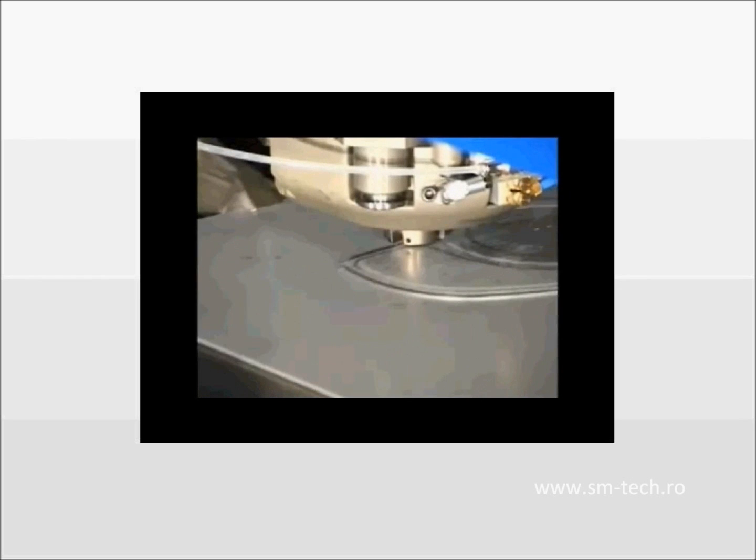If you watch that machine, it comes down to position, fully down to position before it starts moving the sheet. And that's the way many machines operate. They have to bring the tool down to a specific depth before they can start moving the sheet. And when that happens, you do get some distortion, or a pinch is what the question said, at the beginning of the cut.